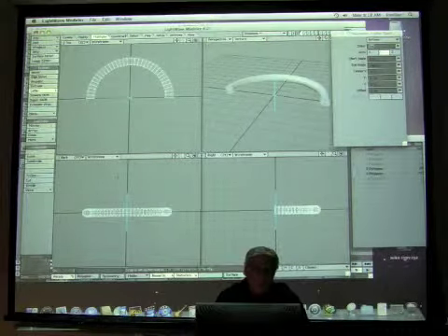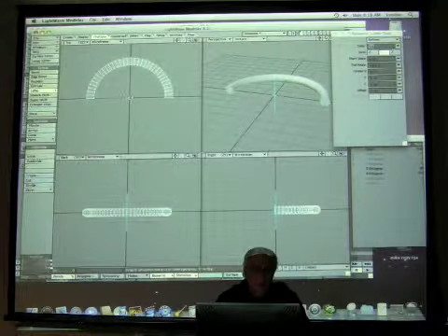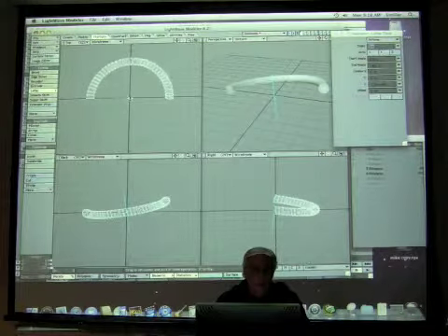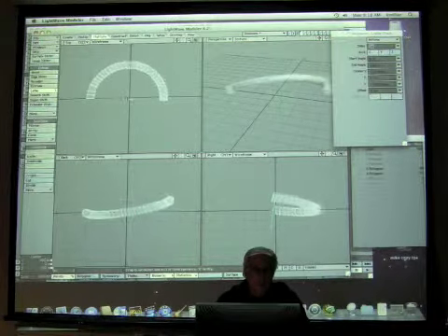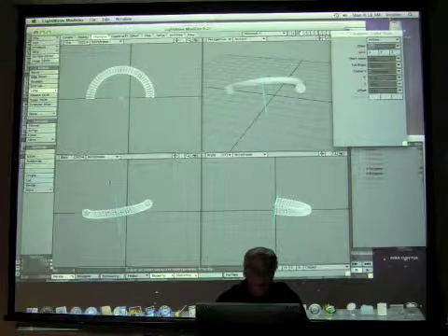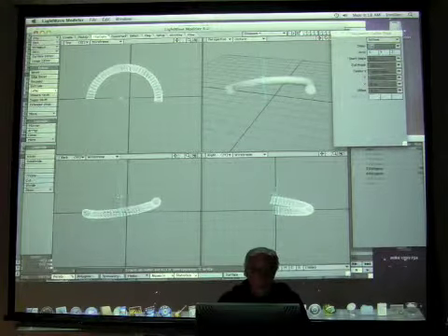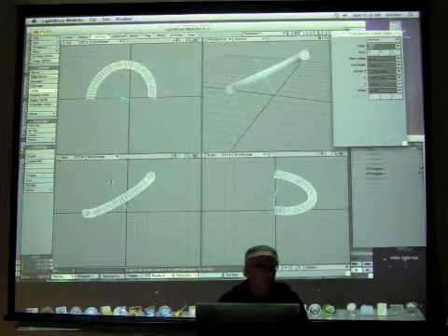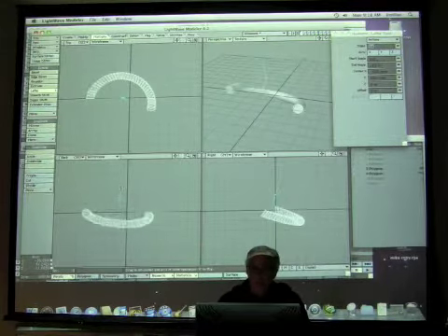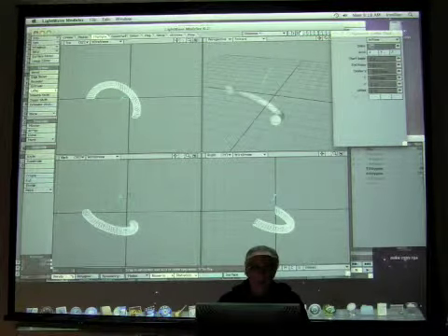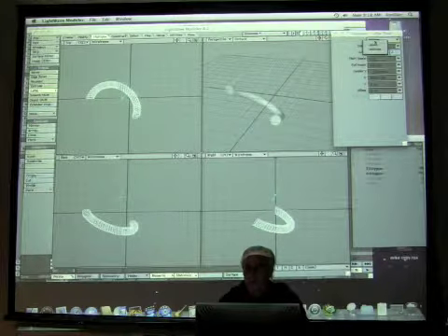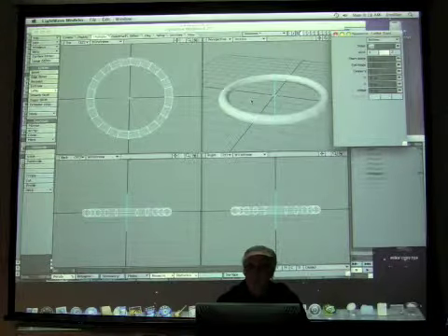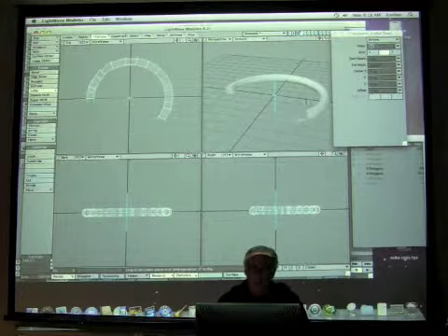Now, some of the other things we can do is, from the center, change the diameter from here. Let me click and move this out, like so. We can also bend this so that it changes the angle from here. This is really difficult to control from here, I find anyway. It's easier to reset and, more often than not, work from the numeric requester to get the result that I want.